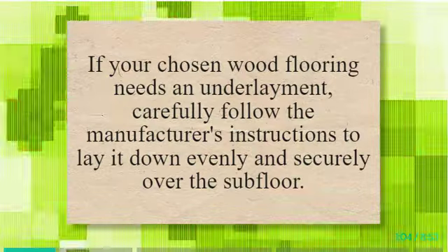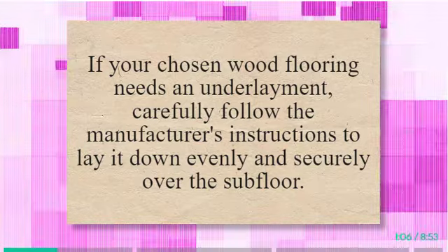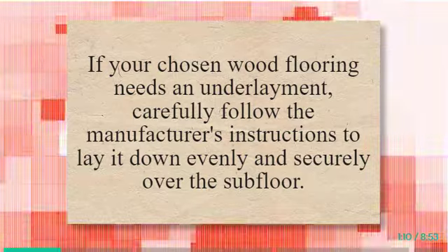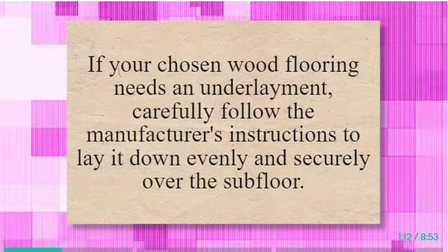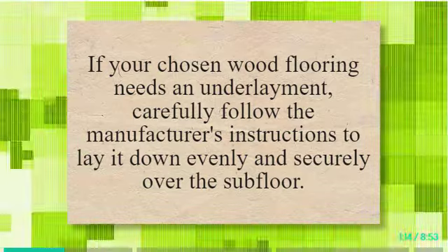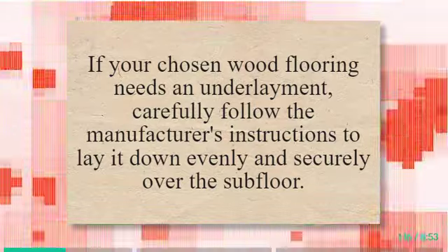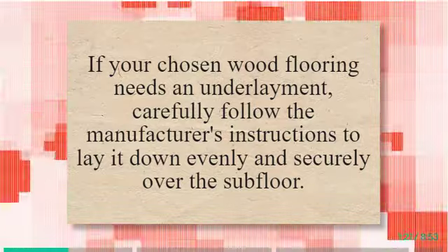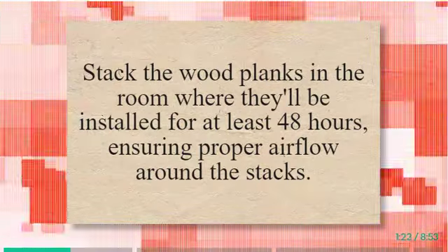Step 3. Install the underlayment. If applicable, some wood flooring types may require an underlayment for added stability and sound reduction. If your chosen wood flooring needs an underlayment, carefully follow the manufacturer's instructions to lay it down evenly and securely over the subfloor.